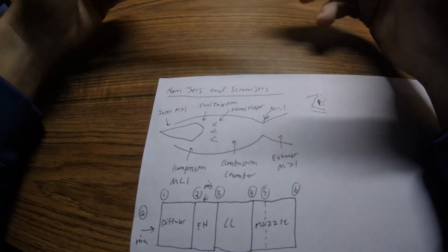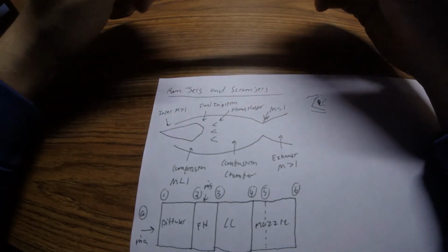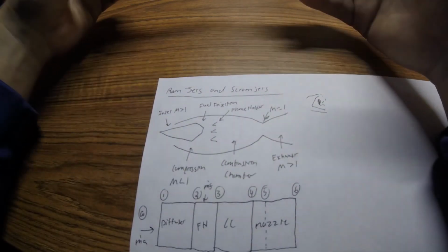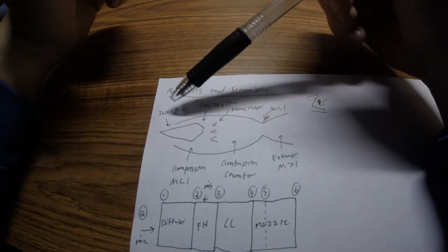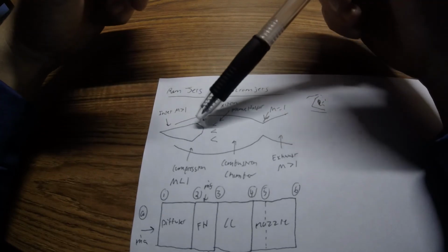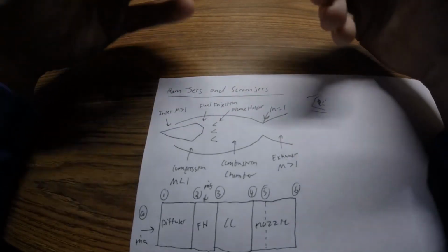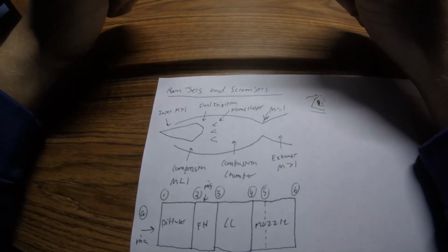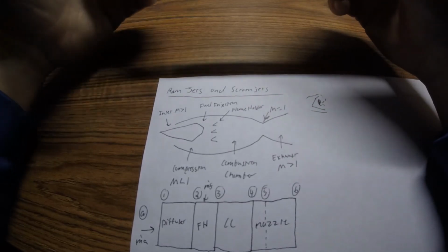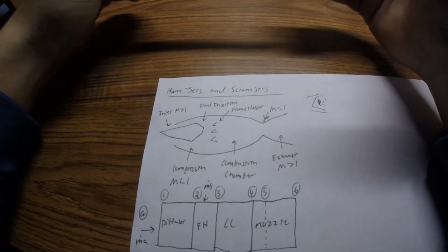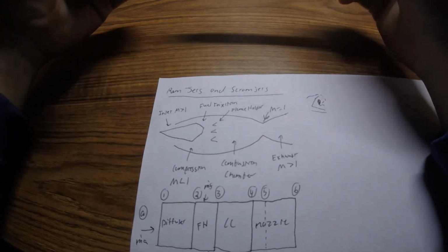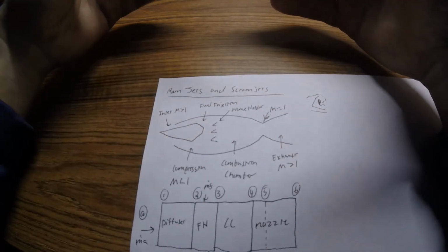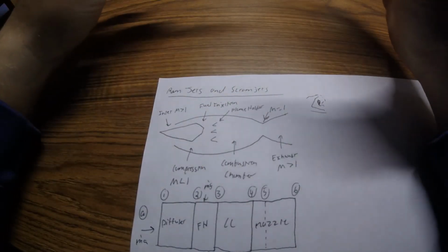The thing with ramjets is that they can't produce any thrust when they're not flying through the air. Okay, so it needs some type of forward movement before it can start creating thrust. The air needs to be moving through the engine for it to work properly, but it can't force the air through the engine on its own, unlike a turbofan or a turbojet engine, where a set of turbines, fans and compressors can suck the air in to the engine and then produce thrust. This can't suck the air into the engine all on its own. It needs to be flying through the air to begin with.